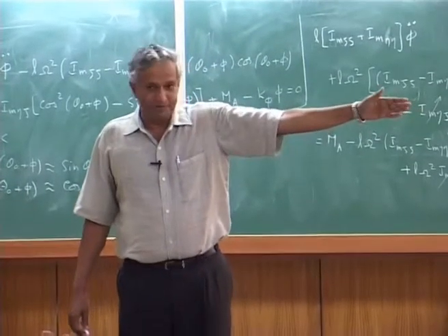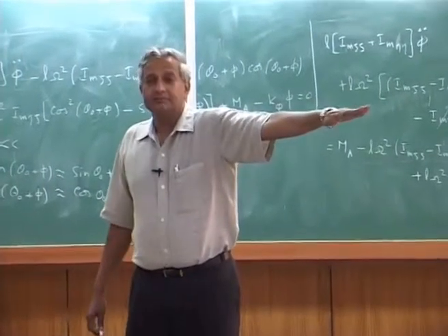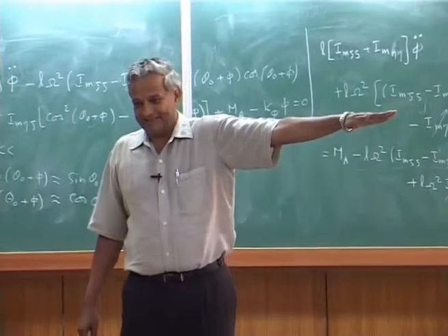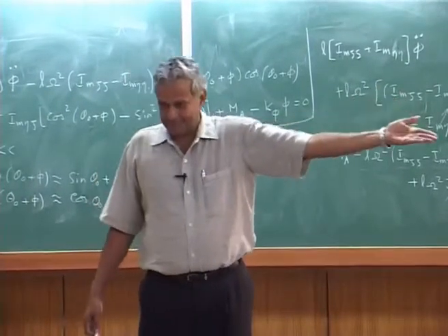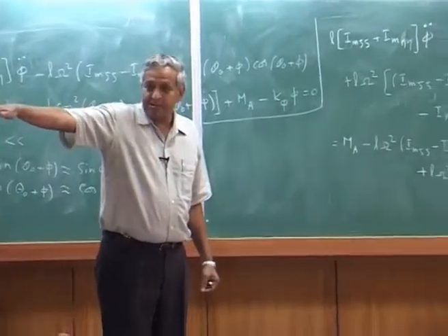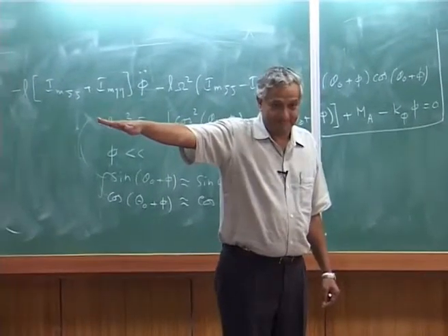In the sense, if you keep the blade like this and rotate it, the blade will always come down. It will be flat. Okay. This is because that is a natural equilibrium position. There is always a nose down twisting moment because of inertial load.